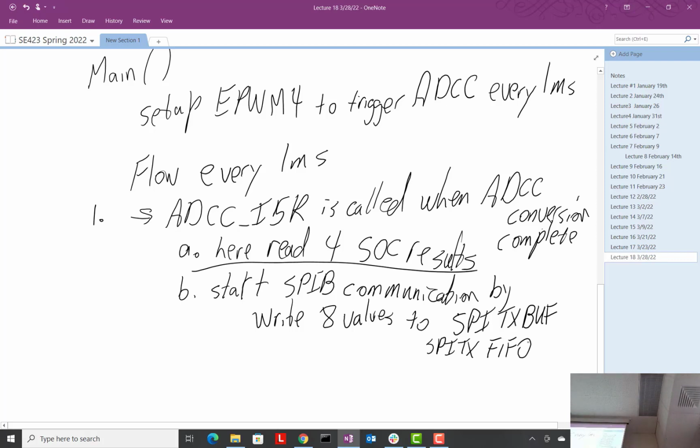Okay? Remember what we did there? We sent 3A ORed with the most significant bit high, so we actually sent BA first, and then BA00. So BA00 was our first thing we sent over. Well, what did we do first? We chip selected it, didn't we? We pulled GPIO 66 low. Then we wrote hex BA00 out to the transmit buffer, or the transmit FIFO.